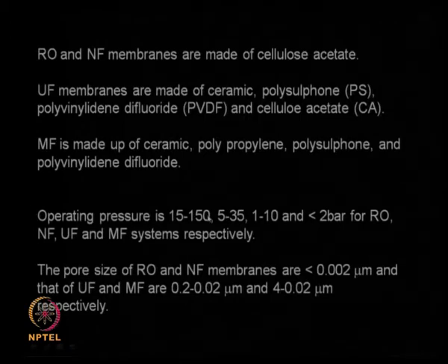Operating pressures vary quite a lot depending upon the type of process we are undertaking. Reverse osmosis, as I said, very high pressure. If you go to nanofiltration, it may be 5 to 35 bar, that is a step less. If you go to ultrafiltration, we are talking about 1 to 10 bars. Microfiltration is almost an atmospheric pressure system.